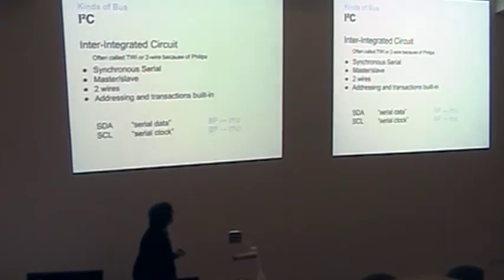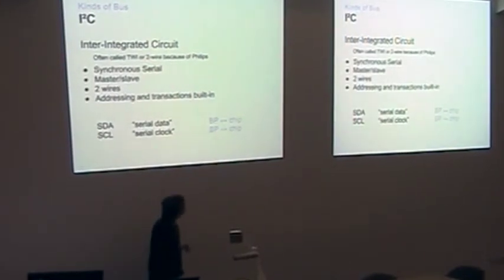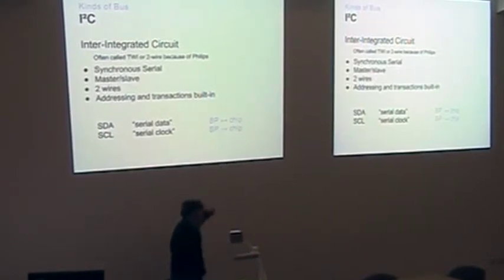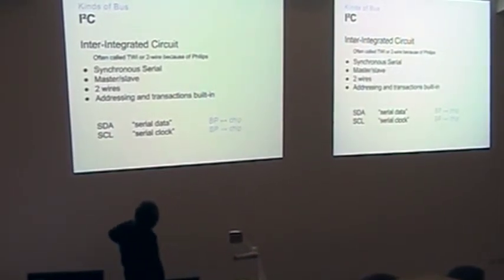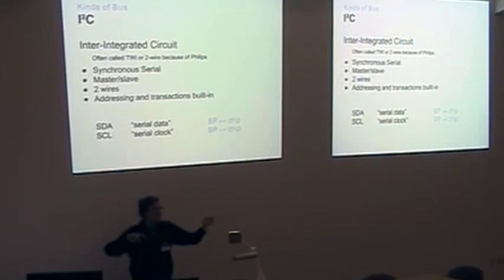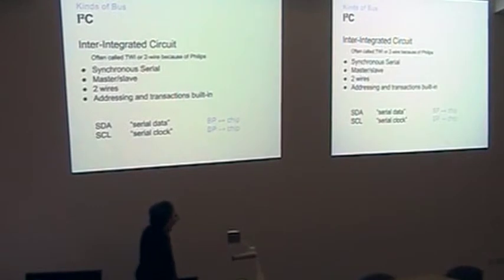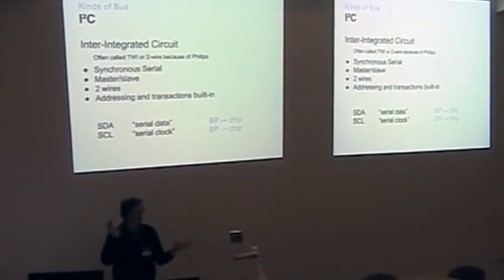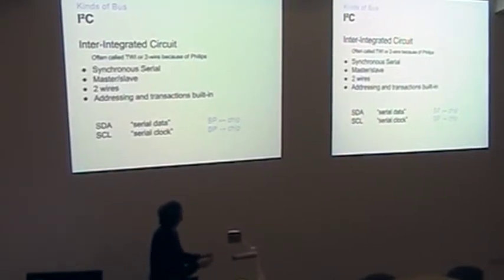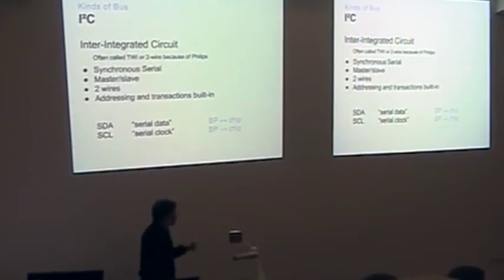There's a little bit more subtle to it, but it has just two lines to it, the serial clock and the serial data. And this arrow here, this backwards forwards thing, single-handedly is the cause of most of the complication in fancy circuits that do this. Because I2C has this wire that goes both ways at various times, depending on what you're doing at the time. And that gets really annoying if you've got one 5-volt chip and one 3-volt chip. Because you can't, so you have to put this fancy little chip in the middle to get them to translate. It gets really annoying.